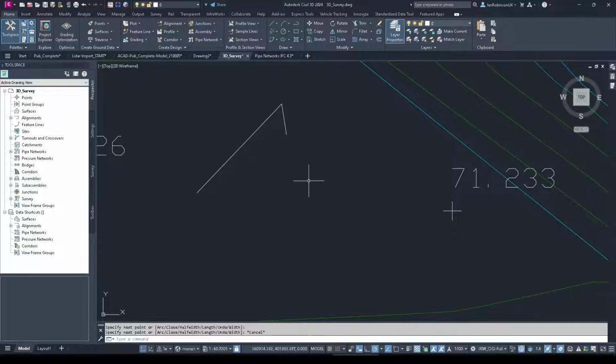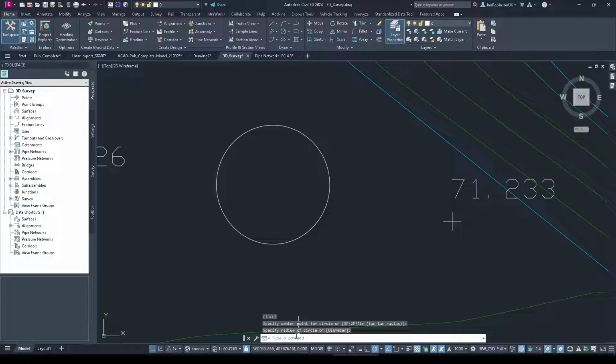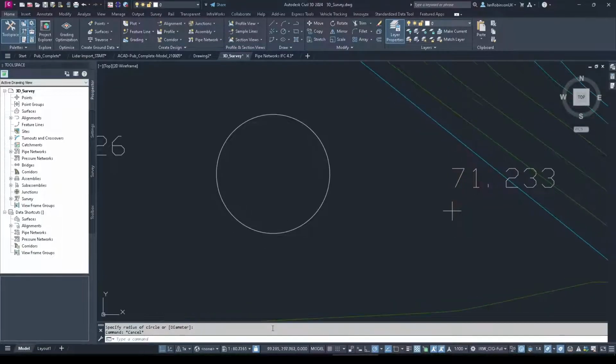But it uses performance. And again, if you're struggling with your machine, simply turn that off and use the command line as a reference instead. That will help. And while we're on with the command line, dock it. If you have your command line here and basically you start doing anything, it's going to create this little transparent 3 lines, etc. Just dock it. You'll have less trouble if it's docked.